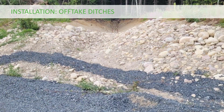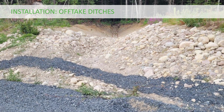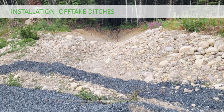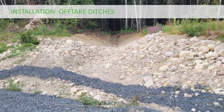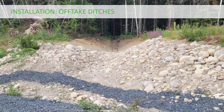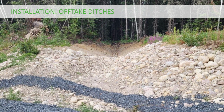Where sites are nearly flat, use simple tools, such as a clinometer, to ensure a gradient is achieved to allow for continuous flow onto the forest floor. Additional earthworks may be required to establish the gradient needed. Ponded water along the length of an offtake is an indicator that additional earthworks are needed to create good flow towards the forest floor.